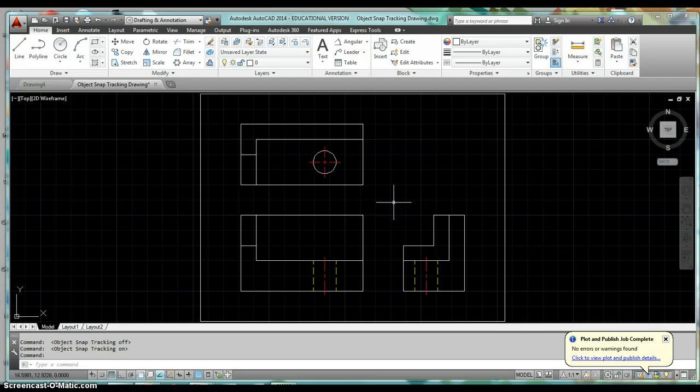Okay, so our first task is to draw in that 45-degree line. If our views are all lined up, so if they're lined up along the bottom and they're lined up along the side, then we should be able to draw a line in here. And when we draw that line, it will be at exactly 45 degrees.